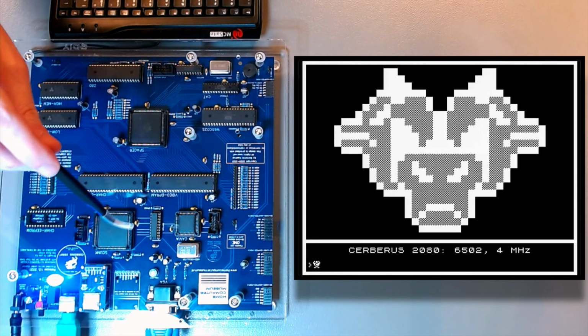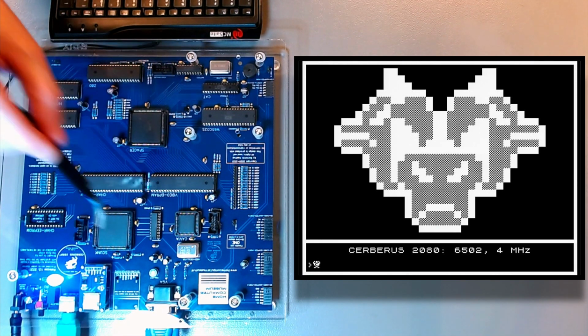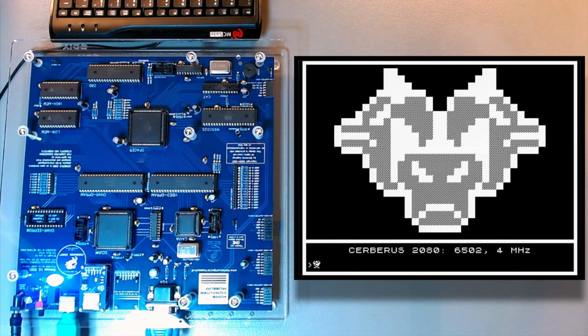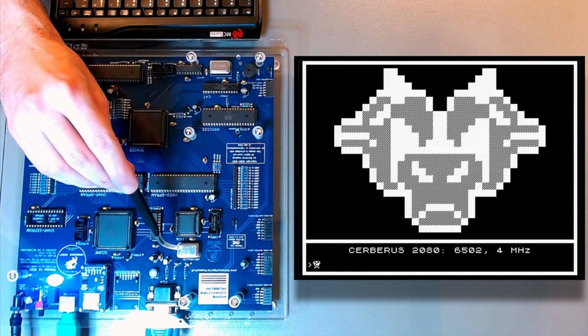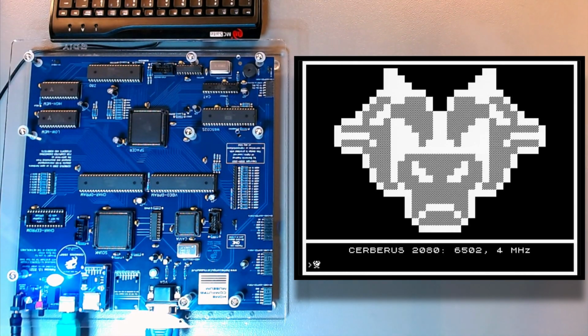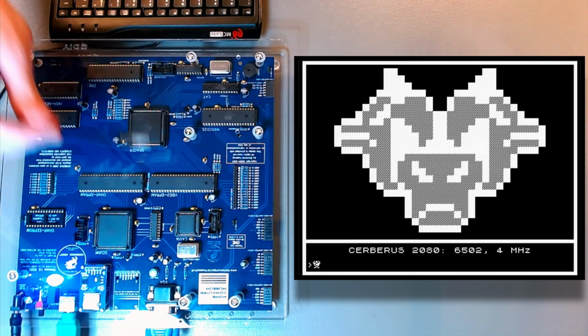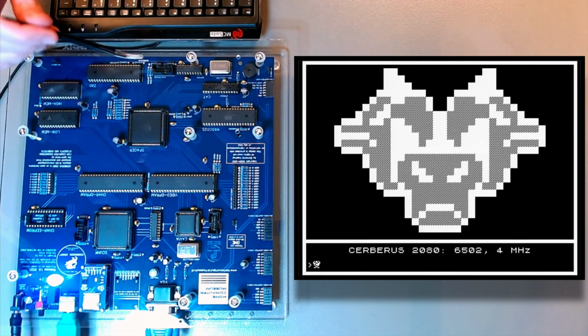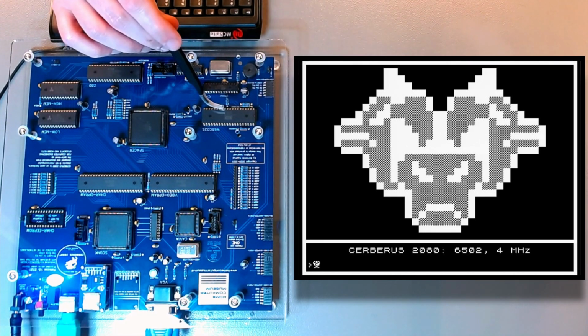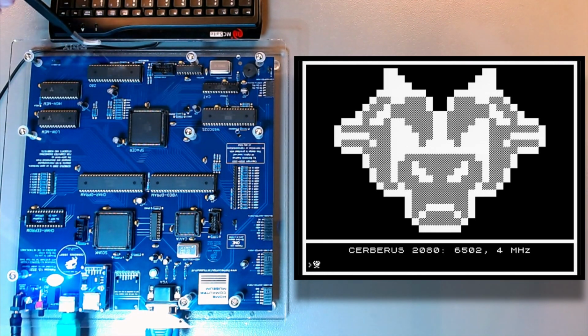Now, this chip in the middle here is just a buffer. It's just to strengthen some signals. This is the oscillator for the video circuit, 25.175 megahertz, which is the standard VGA frequency. Now, on the other side of the video and character memory, we have the computer proper with two CPUs. This is a 65C02 CPU, and this is a Zilog Z80 CPU.